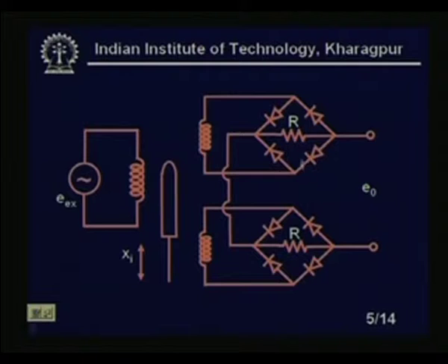You see there we have used 4 diodes here, and we have discussed this in detail. So, we make the algebraic summation of the two voltages to get the voltage output. This is the input to the system, and this is the excitation. Ex is the excitation of our LVDT, xi is the input motion or the input of the system, and EO is the output of the system of the LVDT.